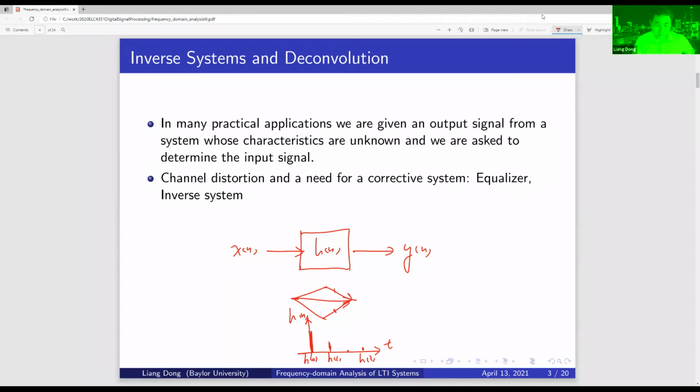The signal X[n] will go through a finite impulse response, right? This is a finite impulse response. The impulse is not just a delta, but it has some other parts here, with a support that expands over more than just one time instant. Then I have the received signal Y. If this is an FIR system that looks like that, with delayed elements here, what will that give us in the frequency domain?